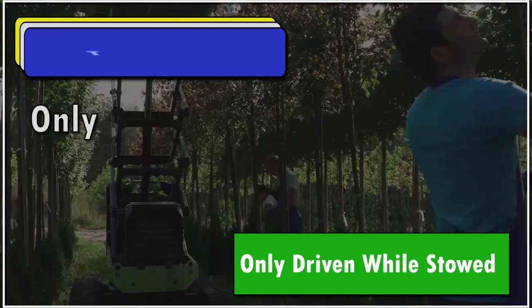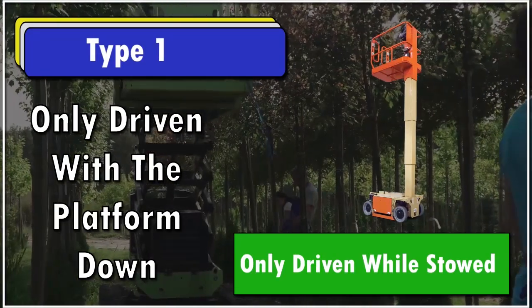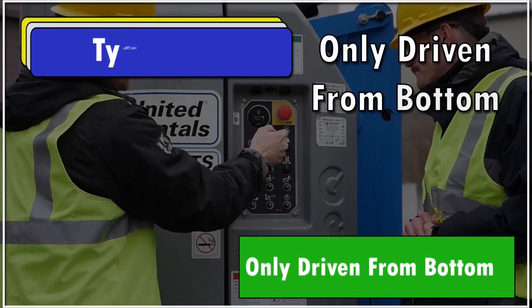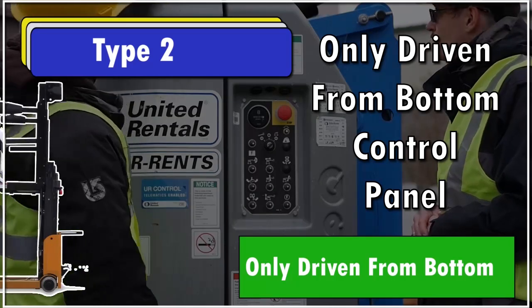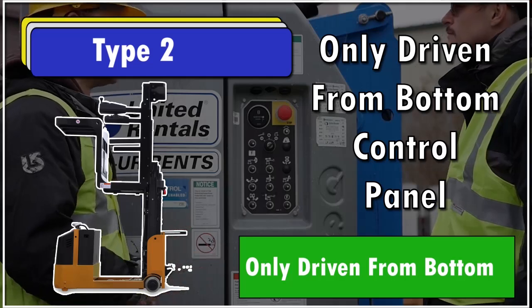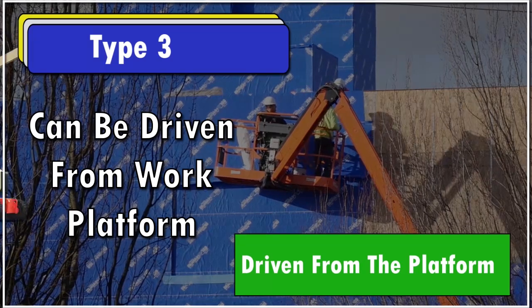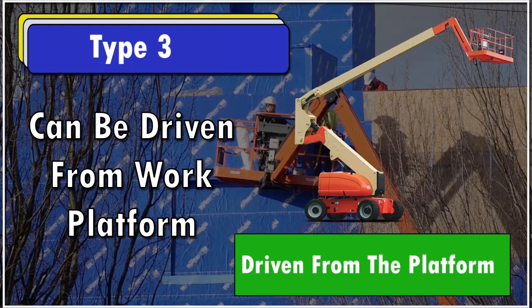Type 1 mobile work platforms can only be driven in the stowed position. A vertical tower is an example of a Type 1 elevated work platform. Type 2 work platforms can be driven while elevated, but can only be controlled from the bottom operator panel. A mobile stock picker is an example of a Type 2 device. Type 3 mobile elevated work platforms can be driven while elevated, and are controlled from the work platform. An articulating boom lift is an example of a Type 3 mobile work platform.